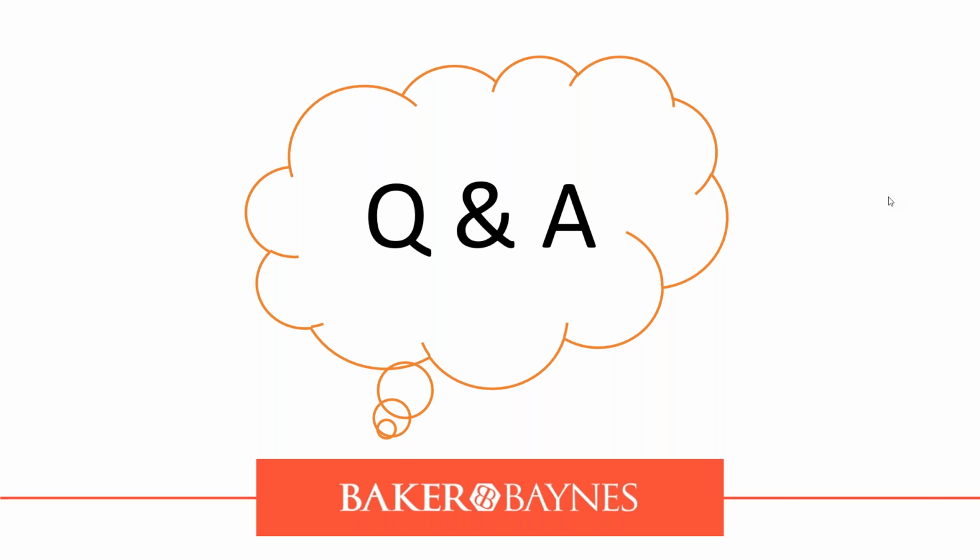Okay, I see a comment that says that the mapping looks a bit complicated. It is a little bit to wrap your head around, but if you follow my video here, that's going to be uploaded soon, you should be fine. Remember, all you're going to do is update the key number for the UK section. So anything that says BS, BS standing for British Standards, you're going to pop that key number to 600. Okay, so 600, 601, and so on, which for the sections you would do.